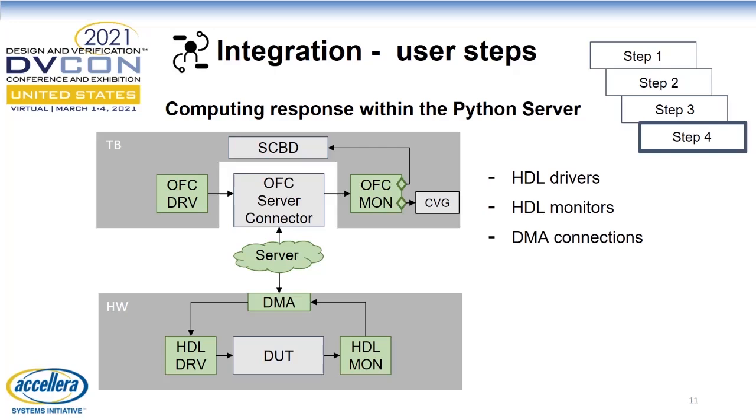The PL side connections and functionality can be defined using the Vivado environment, a tool provided by Xilinx. The DMA IP can also be found and instantiated within Vivado. This IP has AXI stream interfaces. Therefore, the driver and monitor should have an AXI stream slave or master interface. Also, you can export the bitstream file using this tool. Based on the FPGA board you want to use and your preferences, you can also choose another software tool to program the FPGA logic. The OFC Python FPGA component takes care of programming the PL side and finding the DMA modules within the design, given the bitstream file.